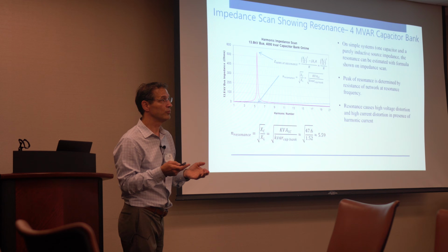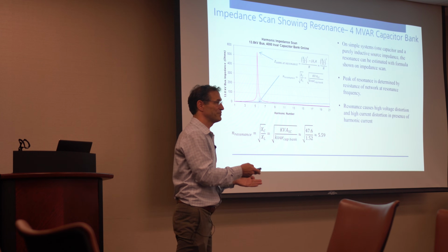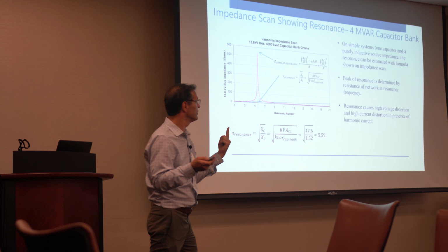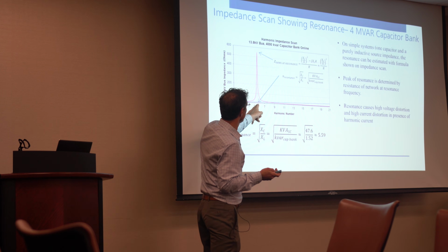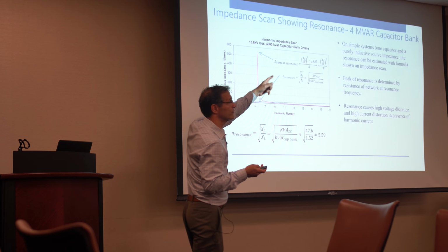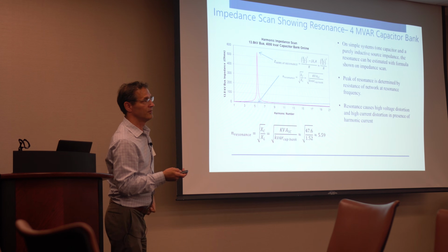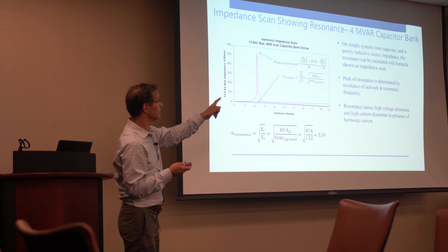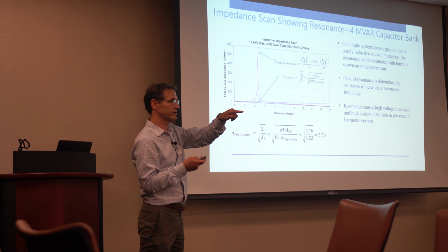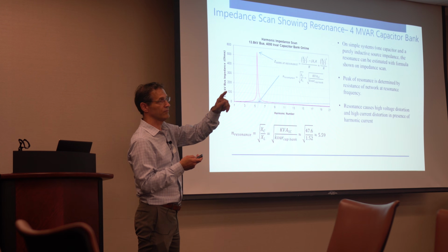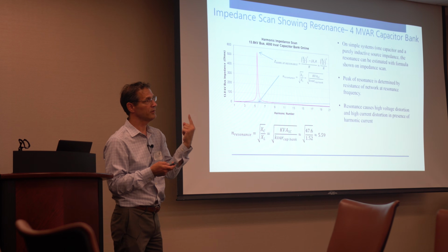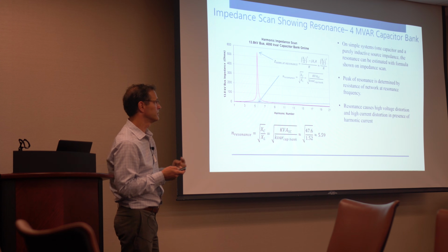So 500 ohms times 1 amp. Now, I only had 1 amp. Before you said 7.5 volts, whippity-doo. Now it's 1 amp times potentially 500. You got 500 volts, which represents a huge voltage distortion. It'd be 500 divided by, in this case, 13.8, so 7.96 kV, 7960. So 500 divided by 7960 would be your voltage distortion for just 1 amp of current injection.